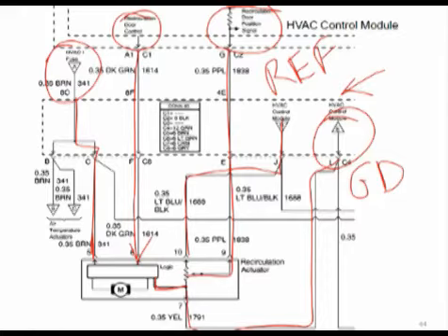Now, there's another series of codes that are available for this door, which are circuit codes, and those would set if the thing was open or shorted or not connected. So we don't have one of those. So that kind of helps us infer that perhaps we're not dealing with an electrical problem, but we're dealing with some sort of a physical problem where the device is not moving to the proper location.